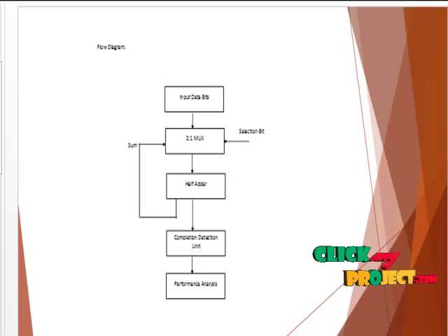So automatically we reconnect and reproduce the process. The 2:1 mux is automatically generated, and then the selection part is automatically generated. The carry skip and carry save adder processing is all automatically generated, and then the adder completes the process.